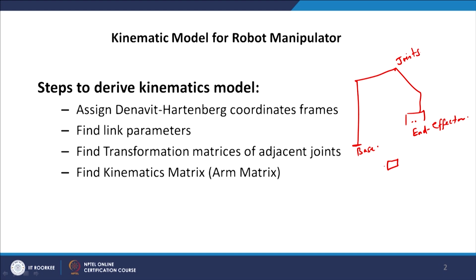Many times we may know the position and orientation of the object with respect to the base of the manipulator. So we should be able to convert that information with respect to the end effector of the manipulator. In total, what we want is to find the relation between the base of the manipulator and the end effector of the manipulator, as well as the object in the environment.